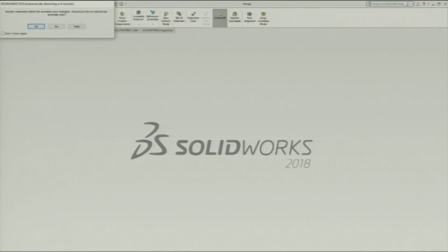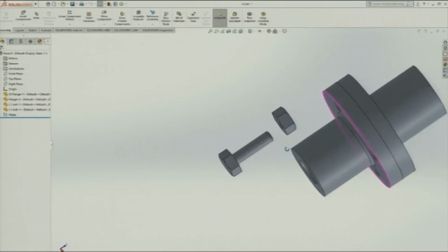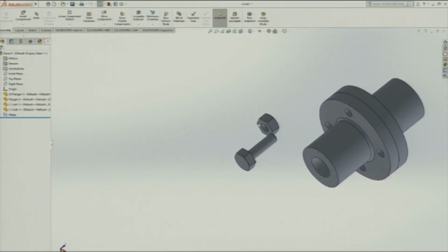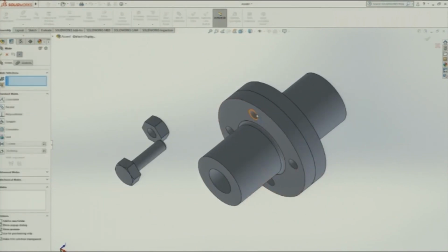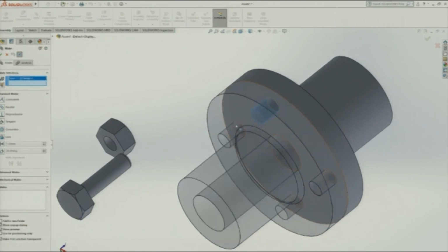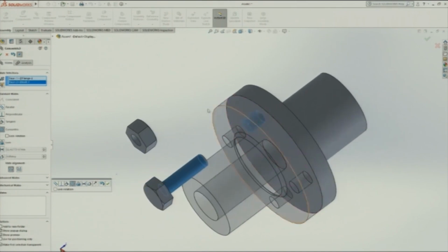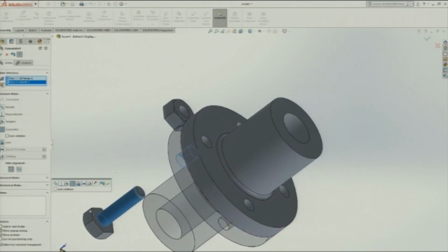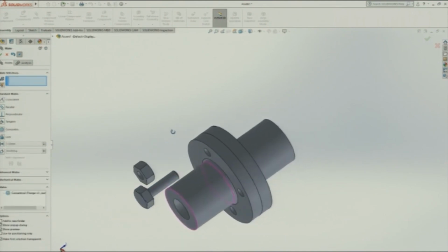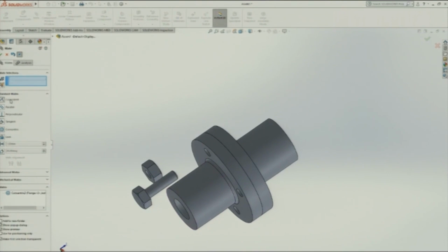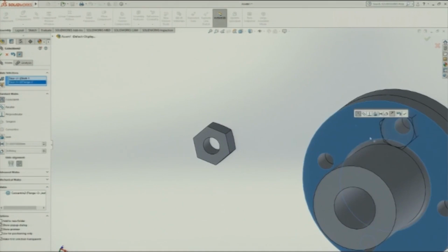So, again I am opening the assembly part. In the assembly, okay, now it looks too good. So, again we have to mate this circle, this hole with this shaft. This is brought concentric, till now it is just made concentric. So, axis it has come into one line, second mate command is between the surfaces. So, we have to coincident the faces, this face and this face. Yes, now it is gone in.